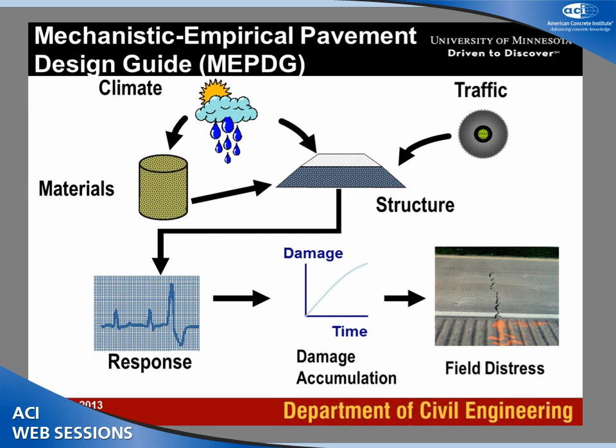Again, I'm not going to discuss it in detail, but basically we're predicting stresses and deflections using Westergaard theory, and we incorporate built-in curl. But built-in curl here is an input parameter which was determined through field calibration. So it's a certain index which allows us to match predicted and measured cracking. It's not predicted rationally, and it may not work for certain regions or for certain construction practices. So it's a major limitation, one of them.